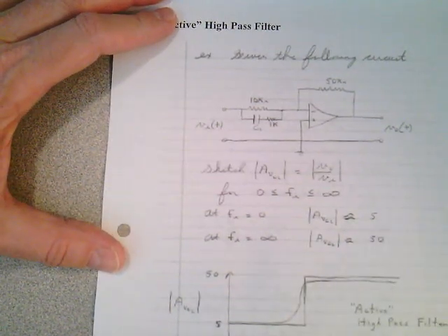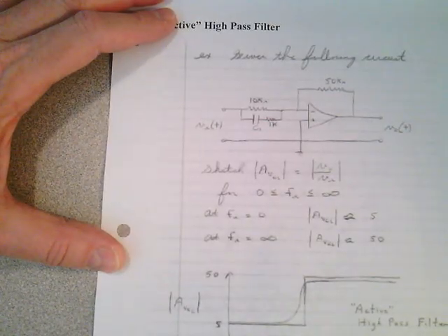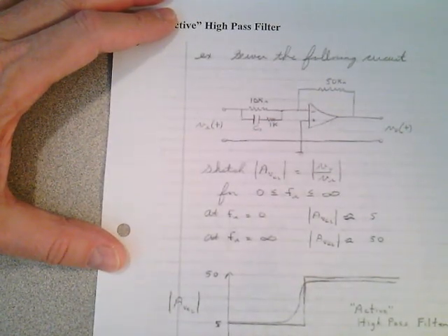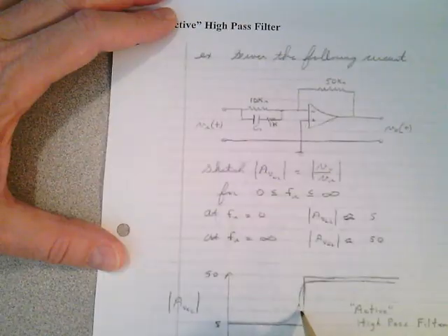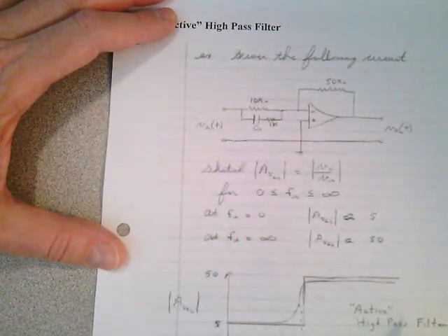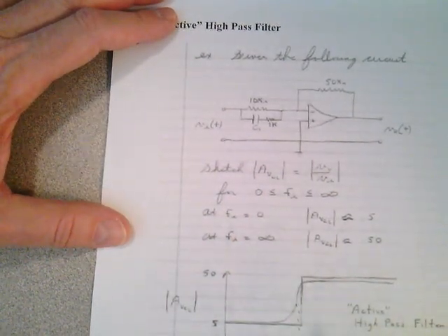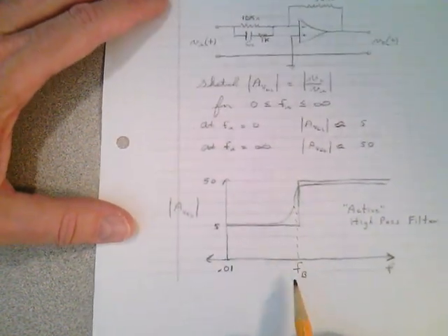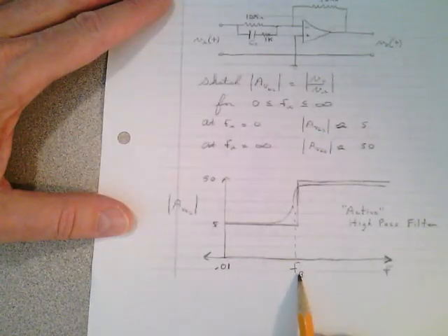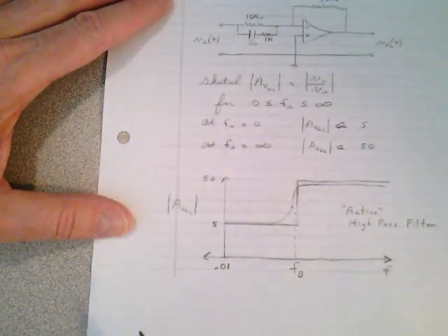So the gain down here at the low frequencies, at DC, let's say 0.01 hertz, is 5. Remember, you can't get to DC here. It just approaches DC. We're not even going to specify this point right here. It's some break frequency, F sub B, which we'll calculate later. Don't worry about that. It's just a time constant between the values of resistance and capacitance. Pretty easy calculation there, but that's not the concept I'm trying to get across here. I'm just trying to have you see that at the low frequencies it has a gain of 5.